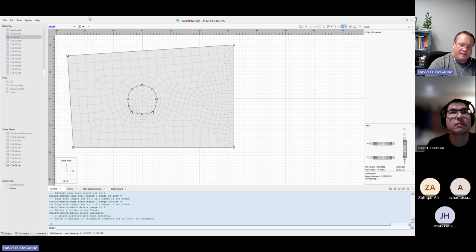It could help if you have big displacements and large strain. Larger zones are going to start to get twisted and not work sooner, so the finer you make it, the longer you delay that. But if you're getting into that situation in this case, then you just don't have a strong enough backfill.